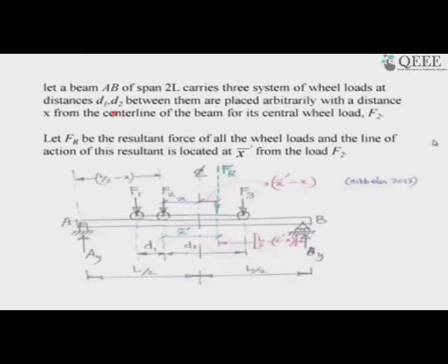The loading may consist of several concentrated loads. The bending moment diagram for each concentrated load consists of straight line segments with maximum value below the respective loading. Hence, it can be guessed that eventually the maximum effect has to happen below one of the loads, but we do not really know the exact position in a combination of loads. I know that it is going to happen below the load, but how to compute that?